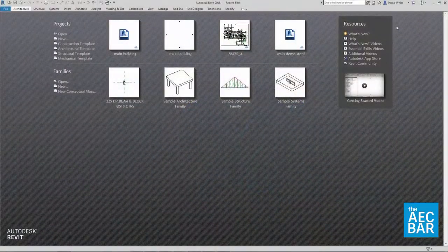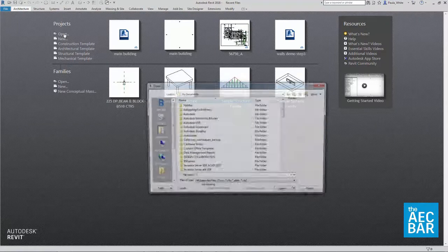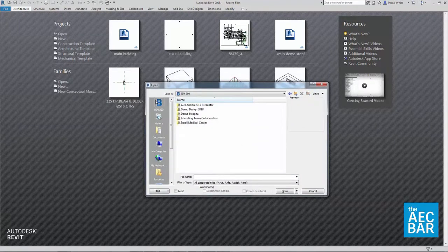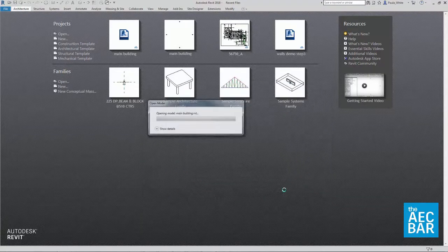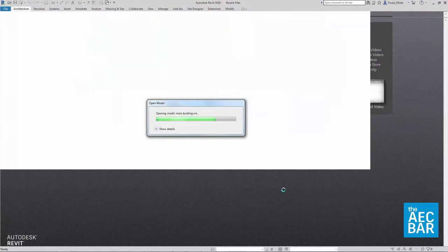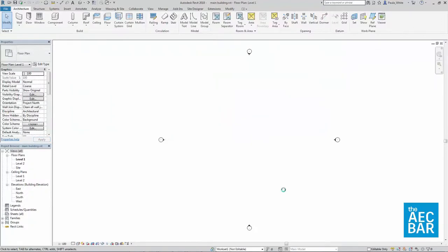It will again list all of the projects that we have access to. So we go into the project that we want to work on. We open the file and automatically we get a local copy on that second machine, third machine, fourth machine, etc. We can claim objects, we can claim worksets, we can relinquish worksets and objects. All of that is identical to what we've seen in the past with work sharing on a central file and Revit server. So with that, that's the end of this video.